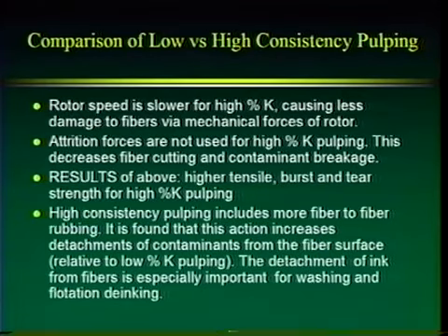Okay, so the results of those two things are that when you pulp with high consistency pulping, you should get higher tensile strength, burst and tear strength than if you pulped at low consistency. So it just shows you that high consistency pulping will cause less damage and give you better properties of your pulp afterwards.